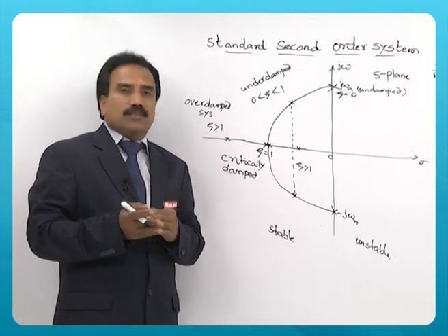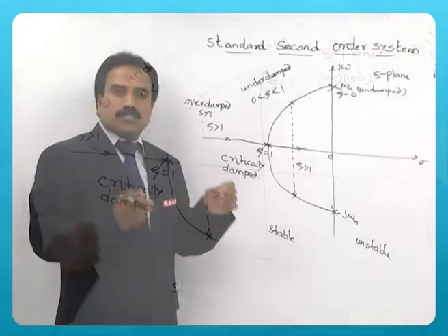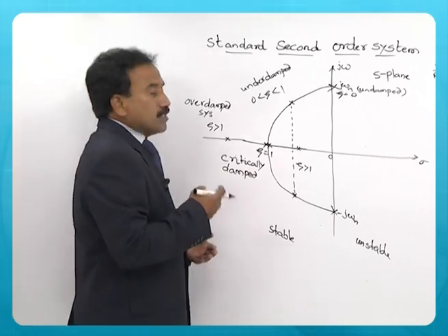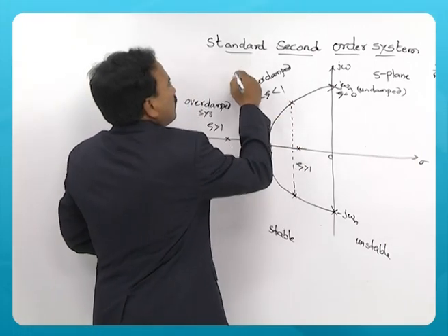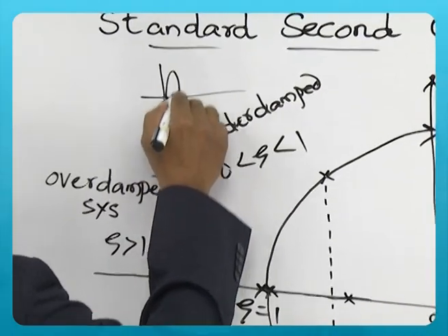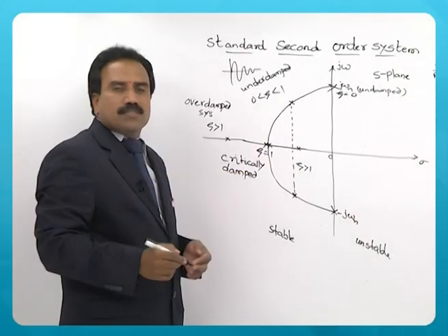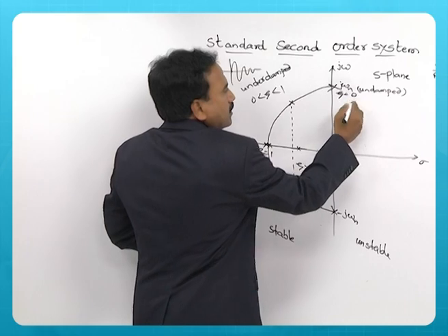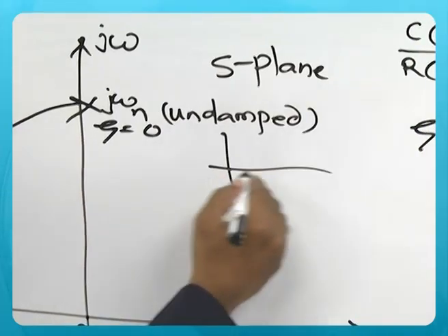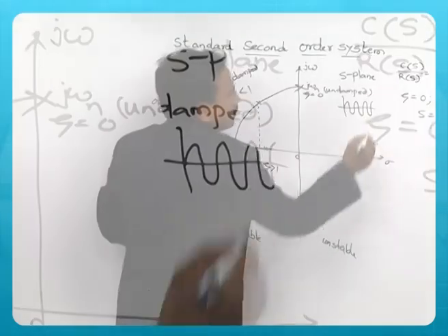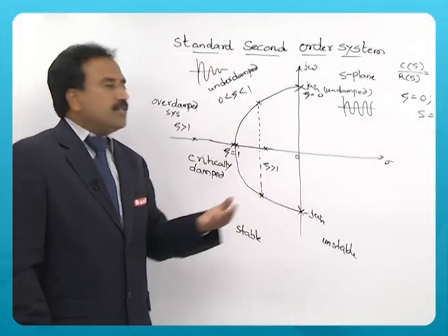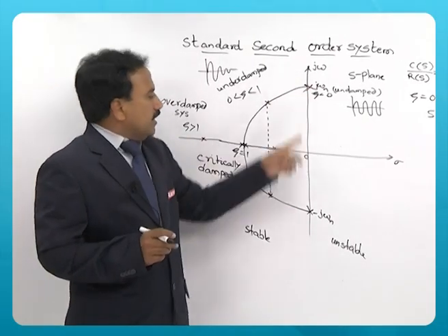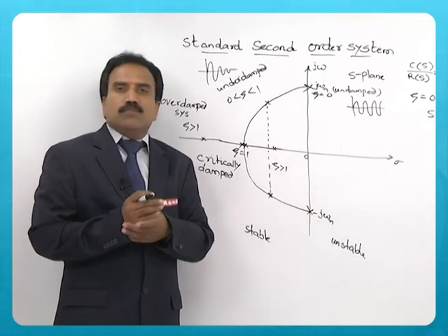But there is a difference. When poles are here having complex conjugate pair, the response for impulse input in the case of an underdamped system will have damped oscillations, means oscillations will die. Without any zeta, if you see the impulse response, sustained oscillations, not good. Sustained oscillations for impulse input is not a good system, means poles are at the verge of instability and it may become unstable anytime.